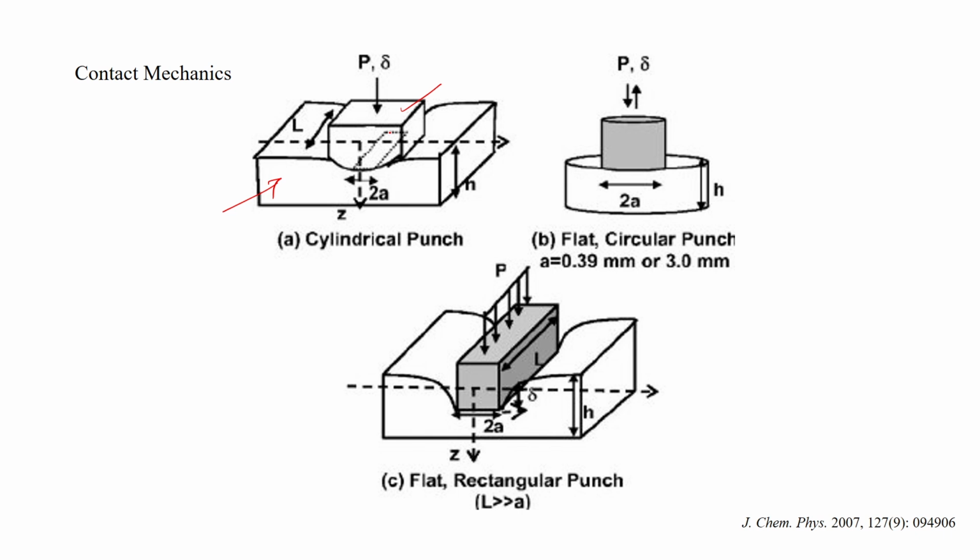So, we are interested to know what kind of deformation happens. Now, this is the load that is applied onto this, so there will be deformation. Now, let us say the load is a pull off load, not a compressive load. Then you want to know, if there is an adhesion between these two surfaces, what is the pull off load that is required to separate them for some amount of adhesion between these two bodies. So, for that we need to know what kind of stress profile occurs at the contact area.